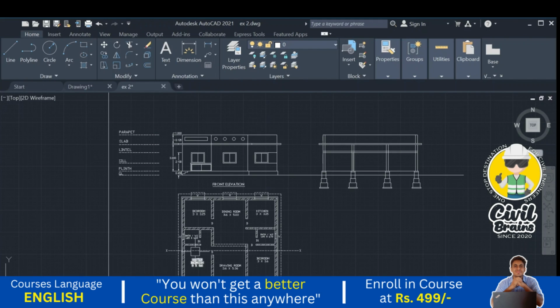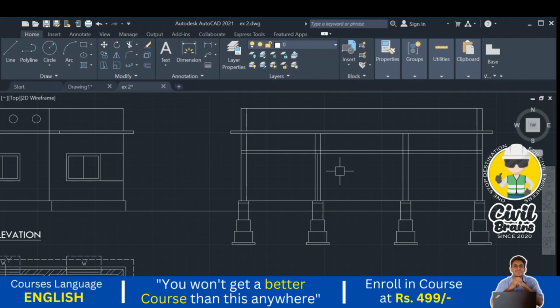Okay, so this is our wall. From here I just take an offset of 1.05 from the right corner, from this wall and from this wall. And what is the height of the window? That is 1.2 meters. So the remaining part I just trim.